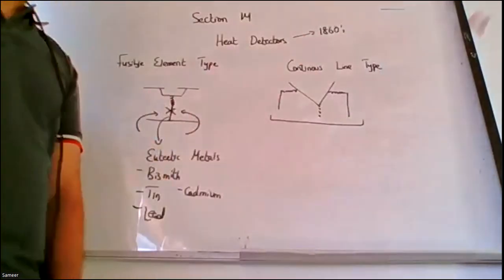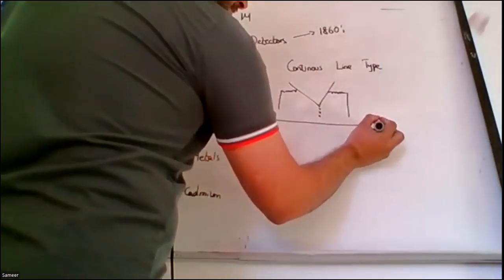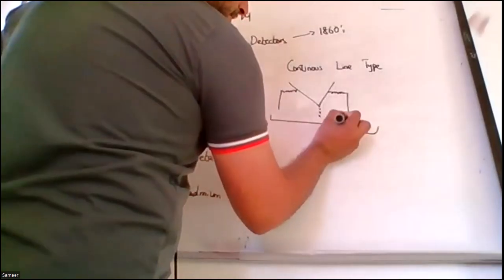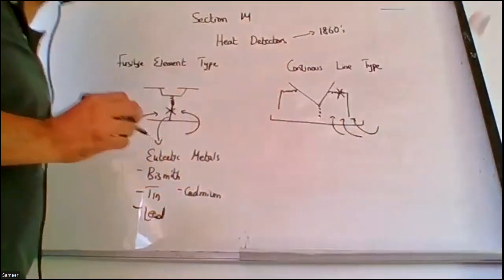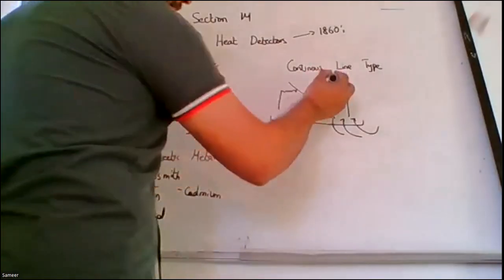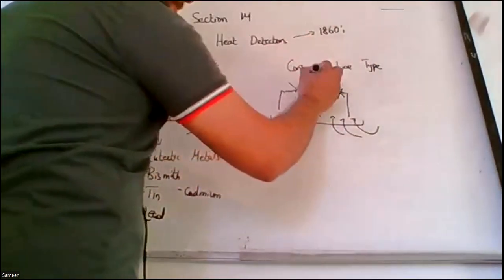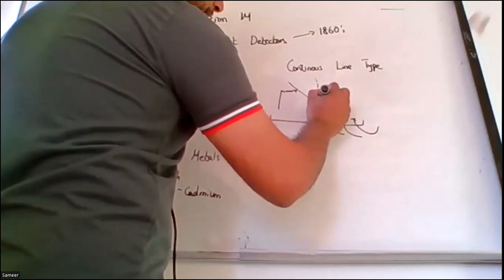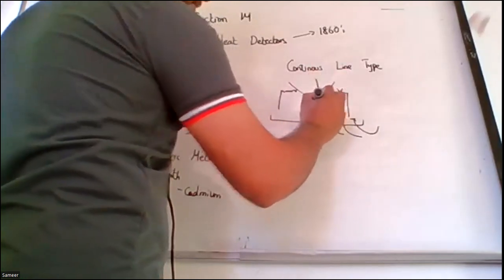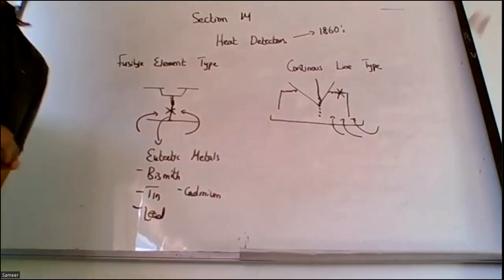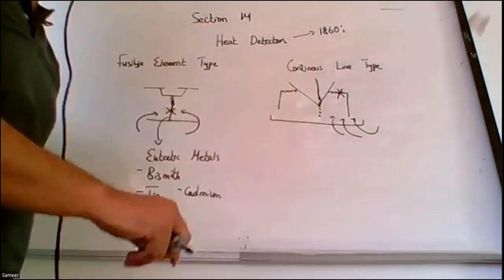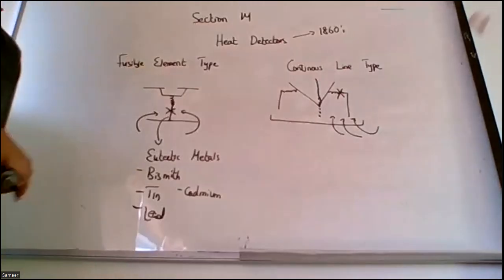Now what happens when the heat rises? Let's say from one portion, one strip breaks down, it releases the copper. The copper comes into a final position in the center somewhere here. Alarm will not trigger. Why? Because there is still an open contact. Heat from here needs to be also increased.